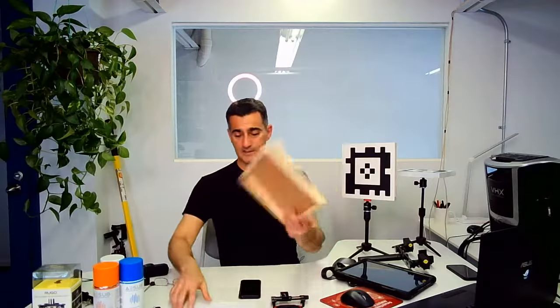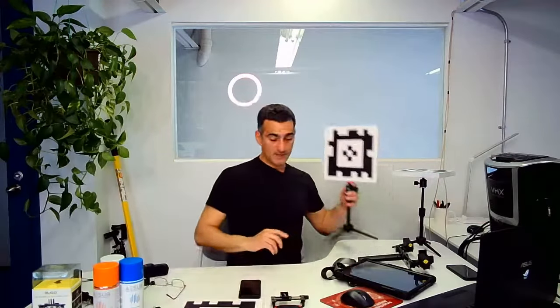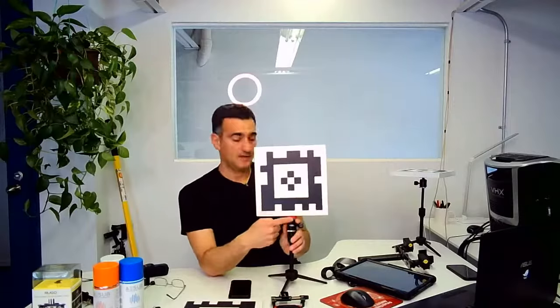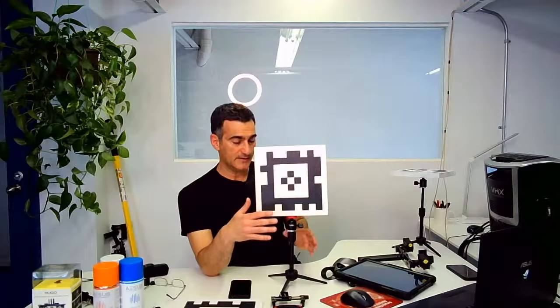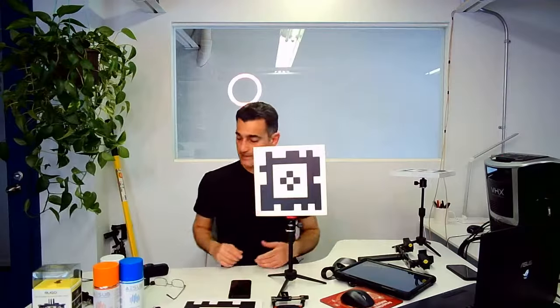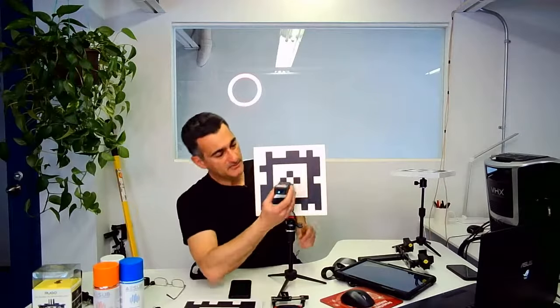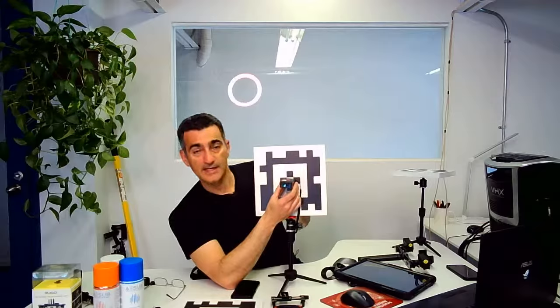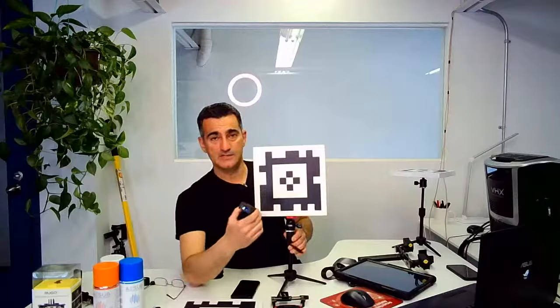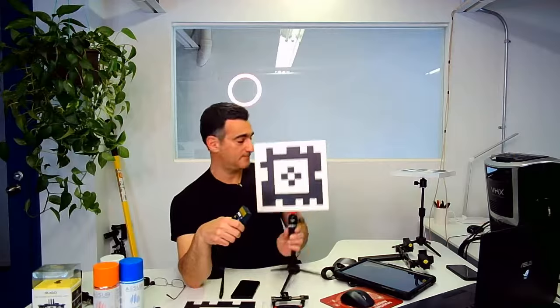It's a little bit larger. This is about 10 inches, or 25 centimeters by 25 centimeters. That's a perfect size for doing cars and things like that. But what I've done is I've mounted it on a tripod like this. With two of these, I can take something like a laser disto, and basically put them face to face. So I go to the center and take a reading. I point the laser dot to the same target away from me, and then I get a center-to-center distance. I enter that value as the target distance inside of Recon-3D.